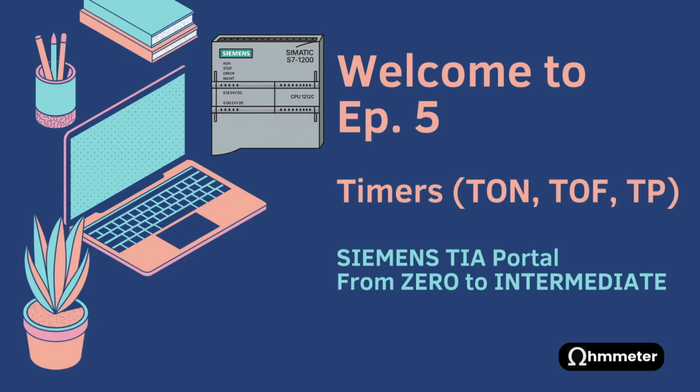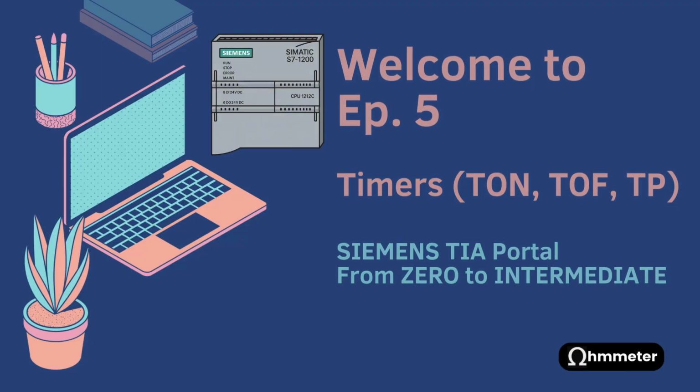Without timers, machines can't control processes over time. You couldn't fill a bottle for exactly 5 seconds, or delay a motor start, or pulse a solenoid for a fraction of a second. Timers make all of that possible. In this episode, we will cover what timers are, three main Siemens timers, T-on, T-off, and TP. We will talk about how they work inside the PLC, and then we will apply them to our project by programming the filling station of our packaging line.